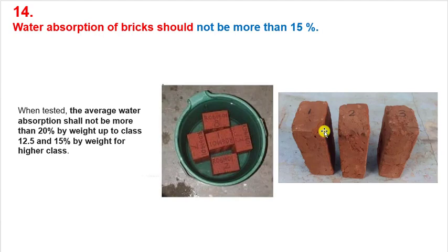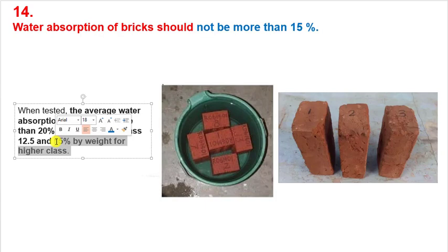So it is recommended that the water absorption of a brick should not be more than 15%. But on average, the water absorption shall not be more than 20% by weight for other classes. But for higher class bricks, the water absorption by weight should not be more than 15%. So that's another important point.